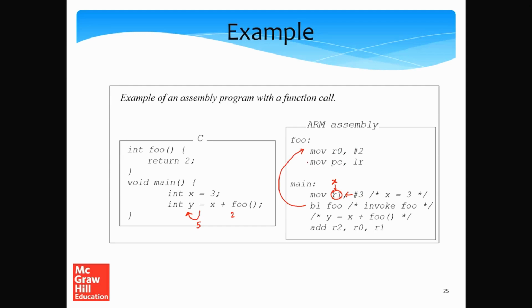The interesting thing is that in ARM there is actually no return instruction. So this is the way that we typically return. Well, there are a few more ways also, but this is one of the simpler ways. Since the program counter and the link register, which is the return address register, are explicitly visible to the programmer, what we do is set the contents of the PC to the LR, which is exactly the same as returning, because LR contains a pointer to the next instruction, which is over here.